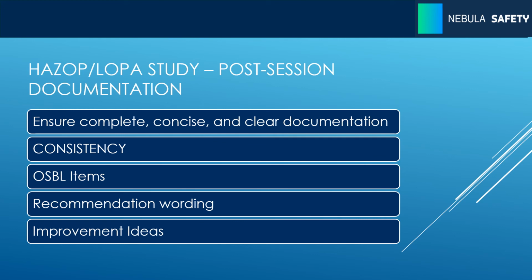You want to ensure that the completed PHA Pro, PHA Works, whichever software you're using to record, is complete and includes all the equipment used within the process. This includes interconnected processes such as utility systems. You want to ensure that the consequence description is concise and clear so that someone can understand the thought process 5 years later. Once again, even 6 months, 2 weeks, a month after concluding these PHAs, the team can come back and revisit the scenario, and it actually is difficult to remember why you made the assessments you did.